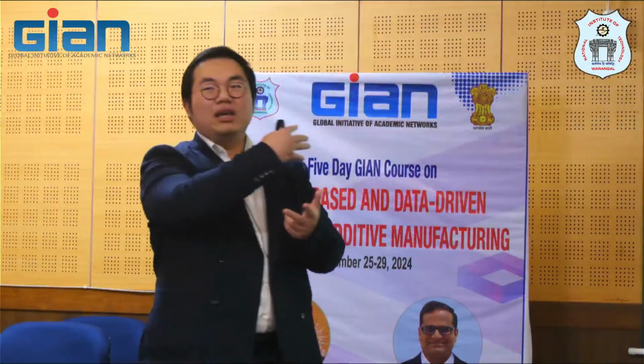I think from the solute transport or solute trapping and the microsegregation study that we do, we understand that there are a few factors that the new alloy doesn't have, because the way the ABD algorithm selects the alloy, it screens out the highly segregating elements like hafnium, carbon, and whatsoever I showed you yesterday, titanium, aluminum. I'm not sure if it's coincidence or not, but it seems that they don't select these for the new alloy composition, or probably because of cost as well. And that's why in the segregation profile you get a homogenized, uniform or average segregation profile. There is no preferred or selective segregation. That's what we found from that work.